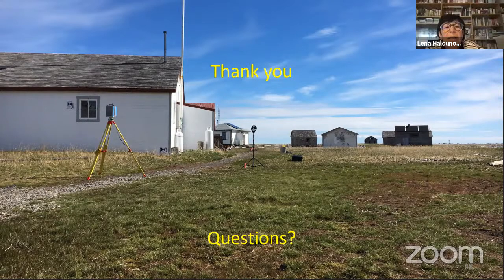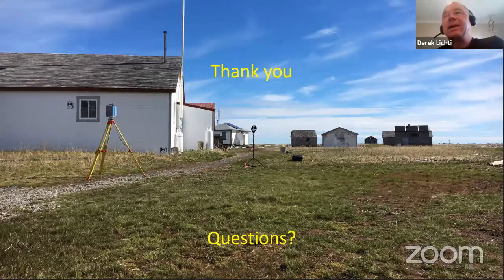Thank you very much. And there is another question from Suni Kushavaha. When the Leica and Faro scanners do not have GPS, how do you suggest precise registration of multi-temporal scans? Well, again, it depends upon the project. If there's nothing available in terms of control points, then it's probably going to be an ICP, or iterative closest point, type solution. But if there are control points, then you would utilize those. So control points placed in some sort of stable portion of the project.